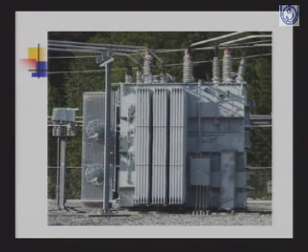Can you explain a little bit more the function of the tap changer you mentioned? The tap changer is being used by most of the utilities to maintain voltage at the 11 kV terminals. For example, if we get lower voltage at 33 kV, then by operating the tap we can raise the voltage. The tap changer is a device which changes the voltage in steps. These steps are specified in IS 2026.